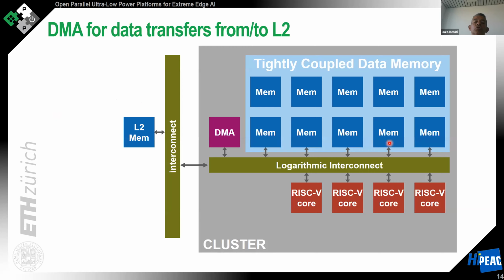So to bring this back into the architecture, once we have provided these services for sharing memory, sharing peripherals, and sharing functional units, we can get to the next point. The next point is that the memory that you can access locally to the processors through this interconnect is of course a small memory, because remember, this memory can be accessed through the interconnect in two cycles, one for request and one for response. So this memory cannot be huge, otherwise the access time to this memory becomes too slow.